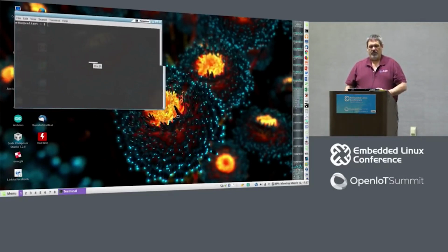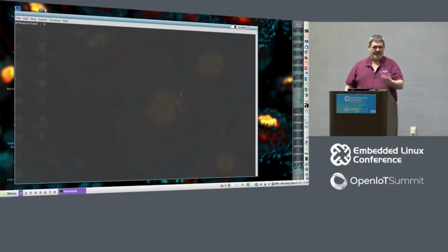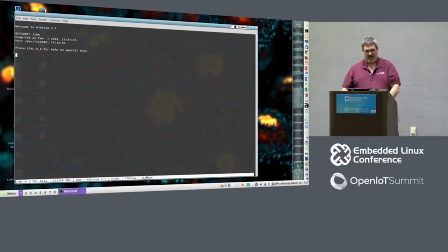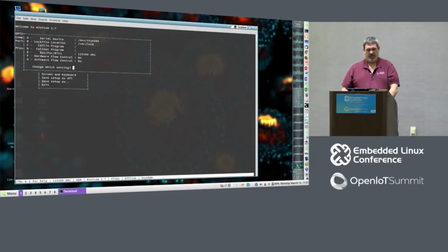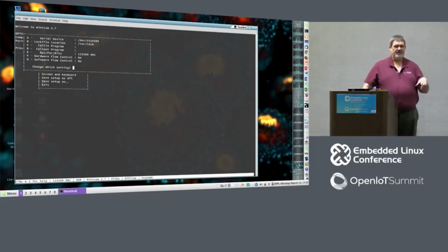Because I've repopulated the serial port, and I did measure some voltages to kind of know what to expect, we'll run Minicom on this, and we will set it up for 115.2, which is usually the speed that a lot of these guys work. It'll be either 115.2 or 9600 baud. Those are the two that they tend to go to.